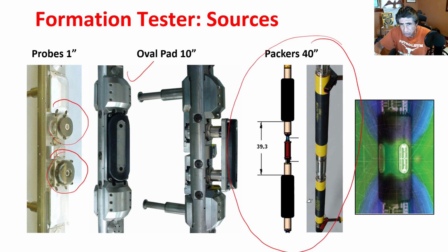And dual packers, essentially what they do is isolate the section of the well that one wants to analyze, and in that section of the well we have flow that is coming equally in all the radial directions. And we do this when you have a large segment of the formation, the amount of fluid that we work with is large, or the formation itself is very heterogeneous, so we want to analyze this transient pressure using a larger volume of investigation.